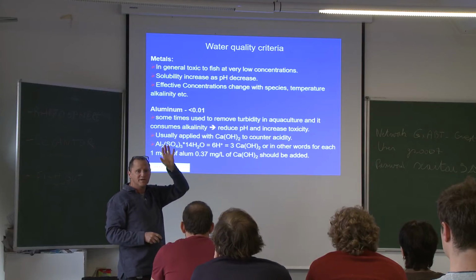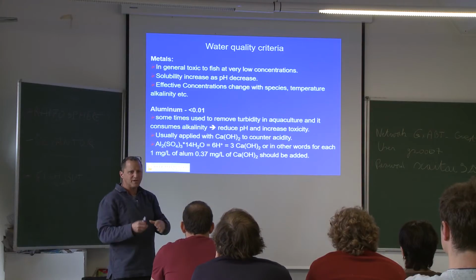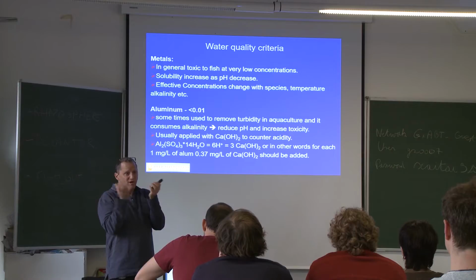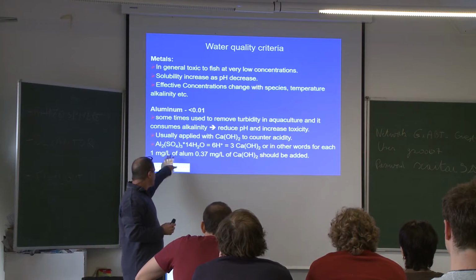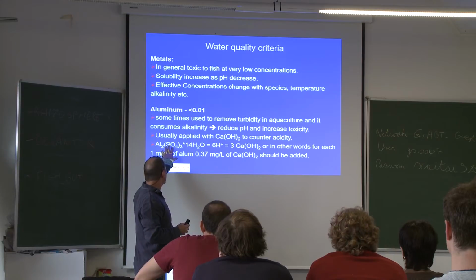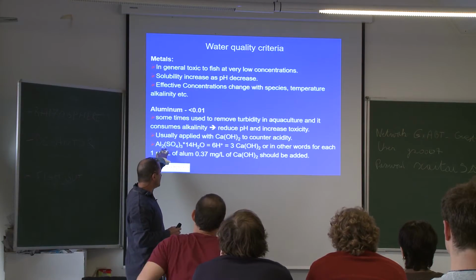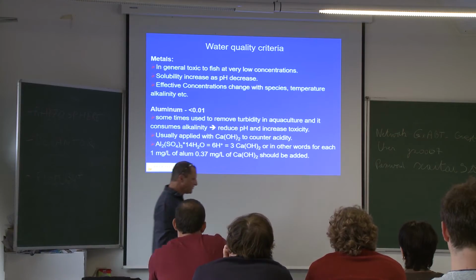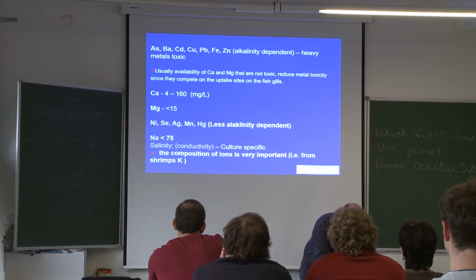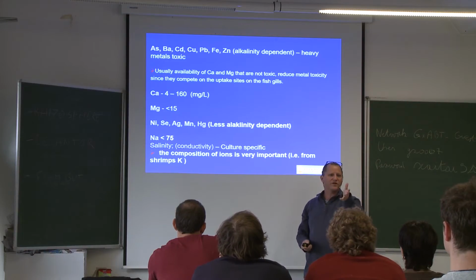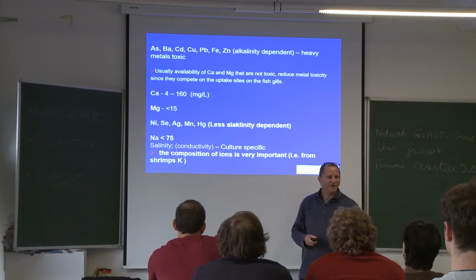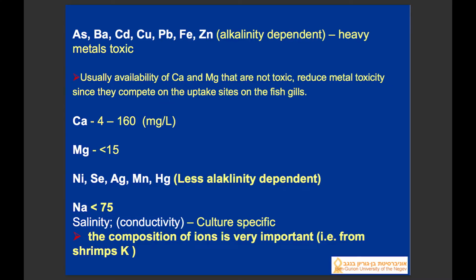Sometimes we use alum as a flocculant to reduce algae or suspended material, and in a wastewater treatment approach it can be used at times as a coagulant and flocculant, or calcium hydroxide. So these are the chemicals to look at that we're using. Or if we use copper for disinfection and things like that, then copper sulfate, we have to pay attention that they're not increasing in concentration.